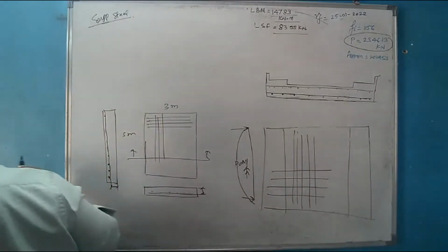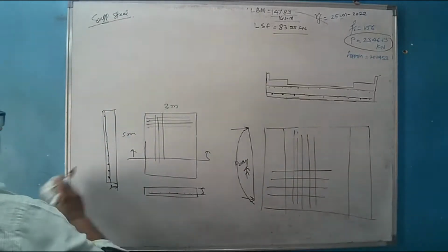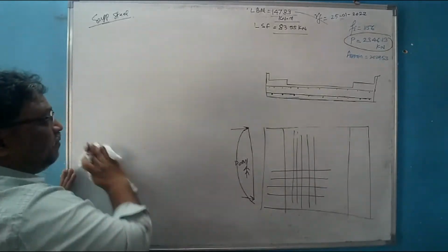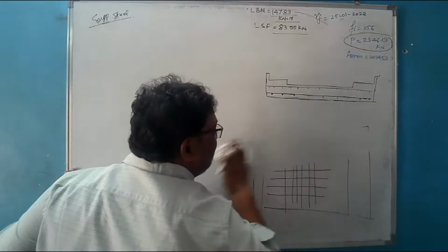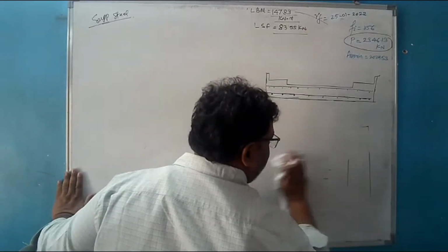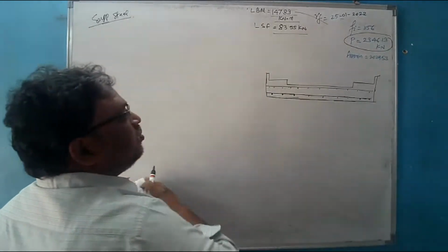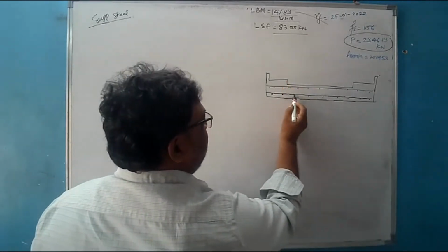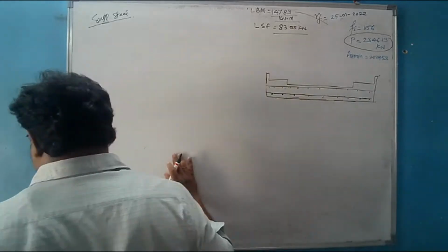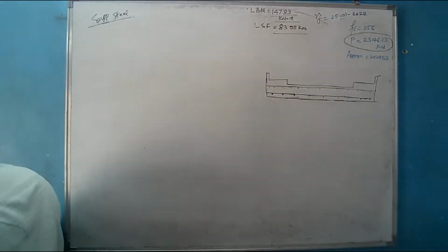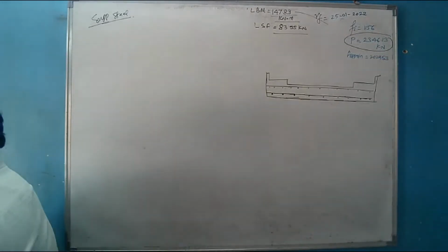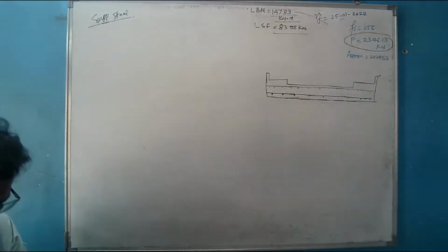हाउ टू कंसिडर द सप्लीमेंट्री स्टील? तो ये जो सप्लीमेंट्री स्टील है हमने पहले बताया जहां पर मूवमेंट ज्यादा रहेगा वो डायरेक्शन में पहले प्रोवाइड करना चाहिए। ये वन वे स्लैब है, तो इन द डायरेक्शन ऑफ स्पैन द मूवमेंट विल बी, सो वी हैव टू प्रोवाइड द स्टील फर्स्ट इन द डायरेक्शन ऑफ स्पैन, फिर दूसरे डायरेक्शन में भी प्रोवाइड करेंगे। नाउ व्हाट आर द गाइडलाइंस फॉर द स्टील टू बी प्रोवाइडेड, सप्लीमेंट्री स्टील और एनी अदर स्टील?